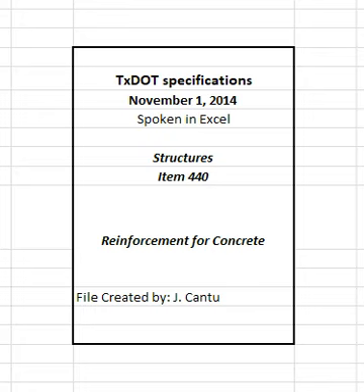Provide bars or wire for spiral reinforcement of the grade and minimum size or gauge shown on the plans. Provide smooth or deformed wire conforming to ASTM A1064.